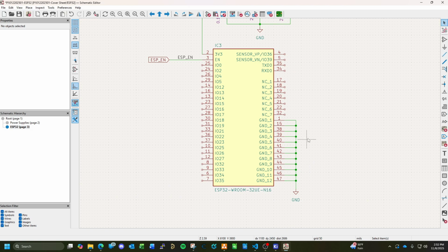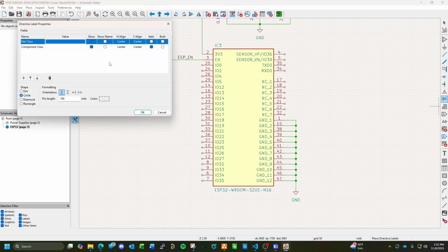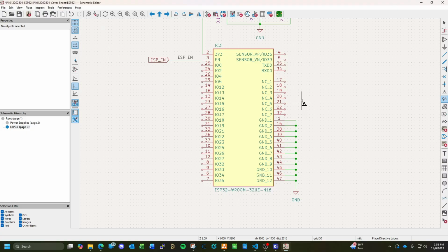All right. Now I think there's directives. Don't need a directive. So in Altium and Circuit Studio, there are no-connect flags. This indicates to the system that these pins aren't used.